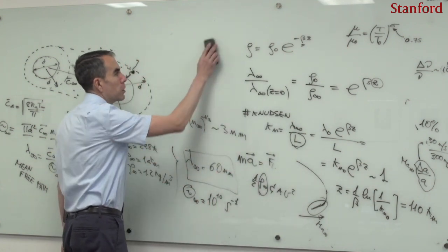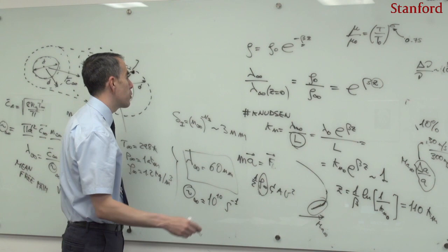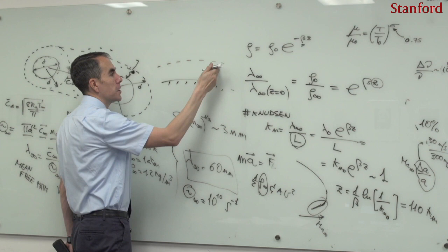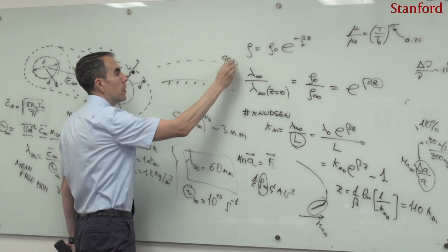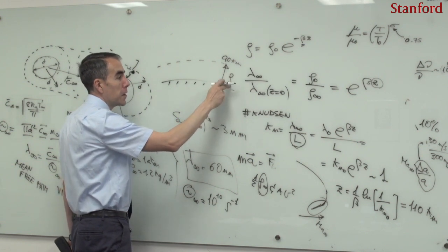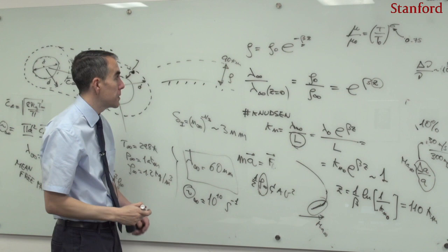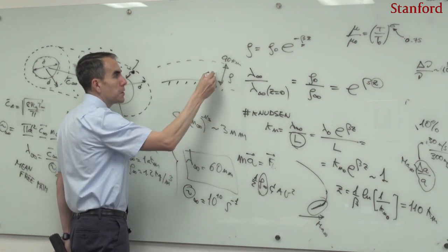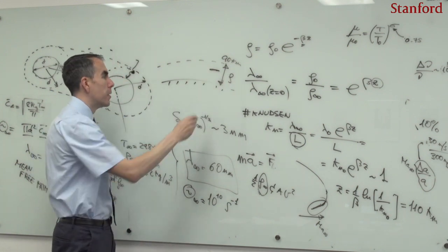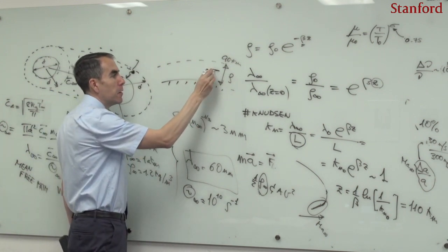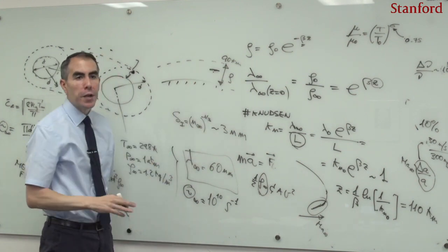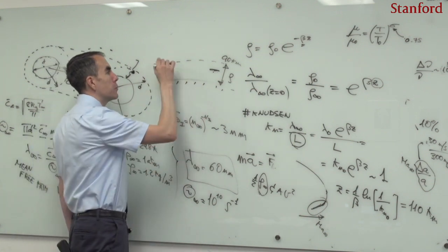Well, one has to take into account the following, and it is that 110 kilometers is already very far away. So if one looks again at the surface, and here the edge of space is located at 90 kilometers or so. We are interested in this region here because this region has density, and the density is the one that brings the aerodynamics into the picture. And it is actually below this edge of space where there is a coordinate that we will be capable of calculating later, where the heat flux is maximum and where the deceleration is maximum. And there, where those two things happen, there is no rarefaction. Rarefaction only exists up here.